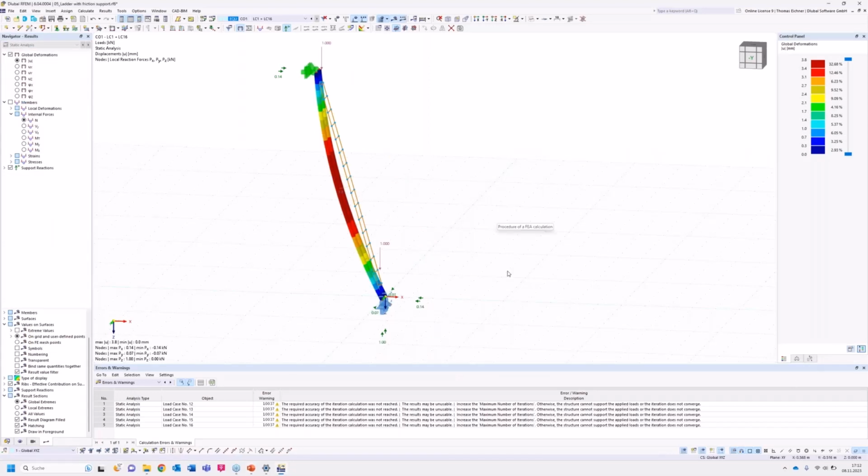And now we calculated it and we can see, yeah, he can stand on top. Why? We have now double force in vertical direction per support. Means also double the allowable force due to friction. And that's why it always helps when someone stays at the first step if the other one is going higher. So then we can go into our next model.